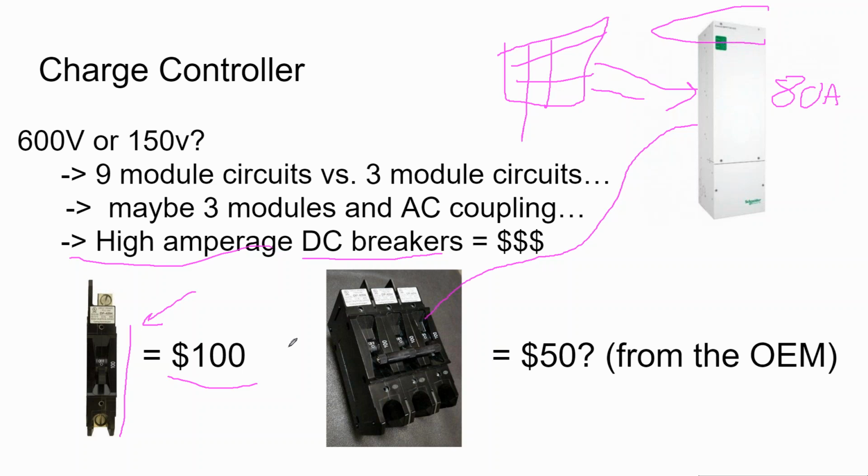It was just one of those things where, oh, we're doing the project, we need the breakers, it's 80 amps, call up, order an 80 amp breaker, forgot to upsize. Well, then the breakers started tripping. I was like, well, I need to fix it. Man, buying $300 breakers is not something I want to do.